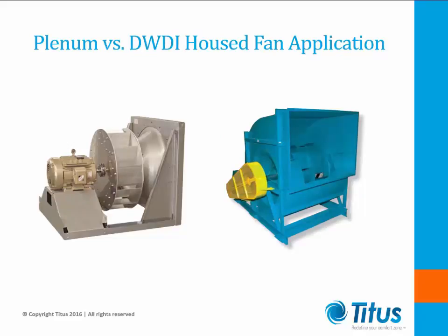To kick things off, we'll look at the Plenum and double-wide housed fan applications. Plenum airfoil fans offer superior performance for many applications. Typical concerns with the fan performance are efficiency, noise, and air velocity profile through components. Plenum fans offer advantages for all three concerns. Additionally, the fans provide flexibility with outlet configurations, reduced mechanical space footprint, and the benefit of direct drive.